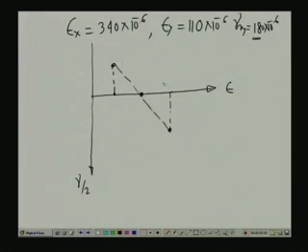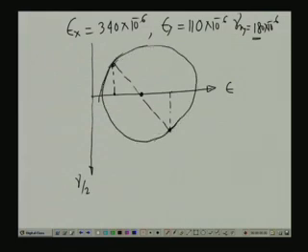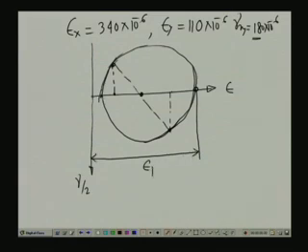and thereby this gives us the center of the Mohr-Circle. And if we plot the circle considering this as center and this as radius, we get the circle. Now, this particular point gives us the point of maximum normal strain, which we define as epsilon 1, and this is the minimum normal strain, which we define as epsilon 2.